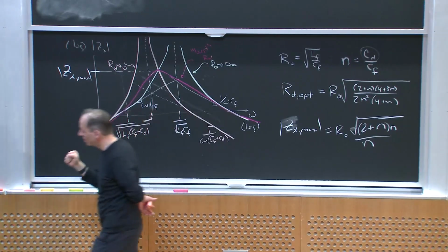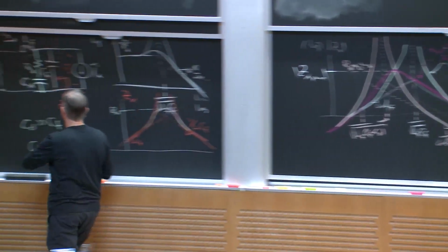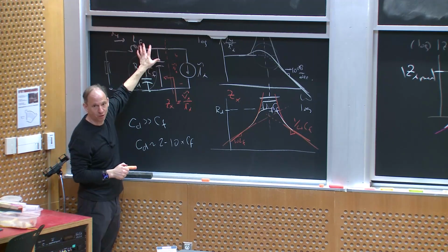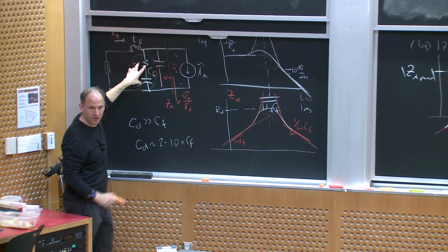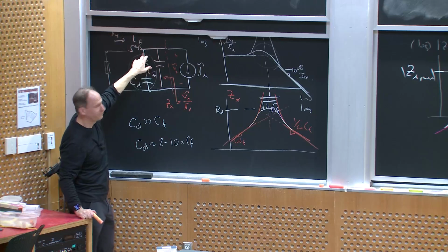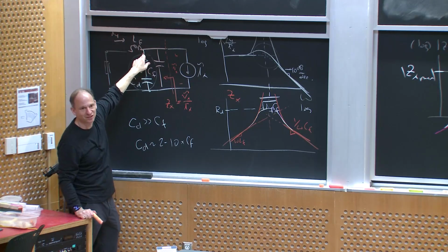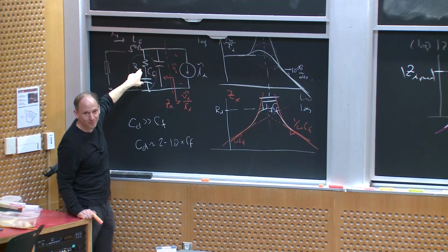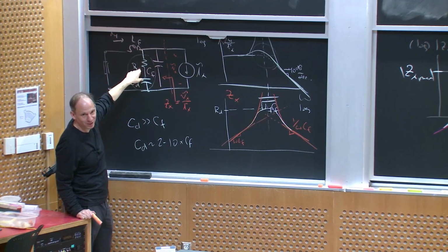On the other hand, CD is really operative near the cutoff, which is orders of magnitude lower. So CD doesn't have to be a great capacitor. In fact, if CD had parasitic inductance, I probably don't care that much. If he has parasitic resistance, I still may not care that much because I can use that parasitic resistance as part of my filter damping leg.